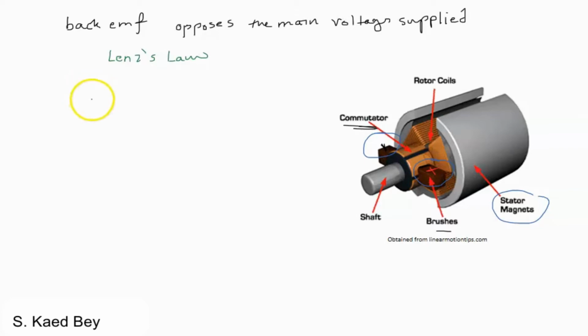In order to find the back EMF voltage relation with the angular velocity, we know that the angular velocity of the motor is directly related to the input voltage by a linear relation where the slope is equal to the voltage constant.